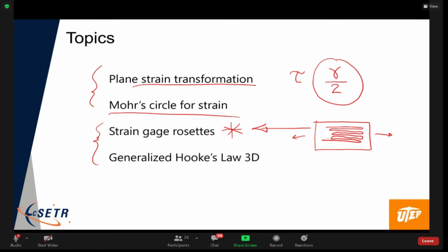And then from the strain, if we know how the strain is related to the stress, ergo Hooke's law, we can then calculate the stress. And this is how it looks. As I said, 99% of all structural experiments where they calculate the stresses, that's how it's done, okay?